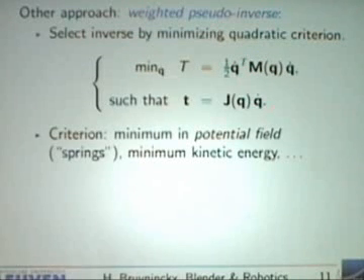And this is the criterion that we put on this optimization. So this is the minimum. I want to spend minimum kinetic energy in doing something, but I still want to have my desired motion. If you solve this, which can be done very efficiently, then you have the motion that I showed you before. This is just one criterion, minimum kinetic energy. You can come up with all kinds of optimization criteria.